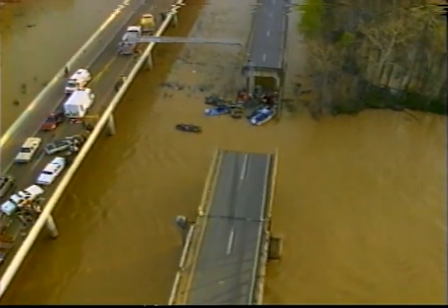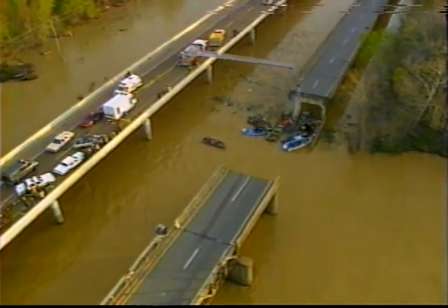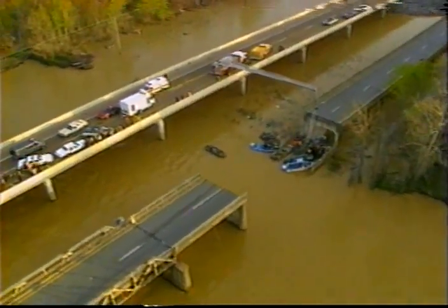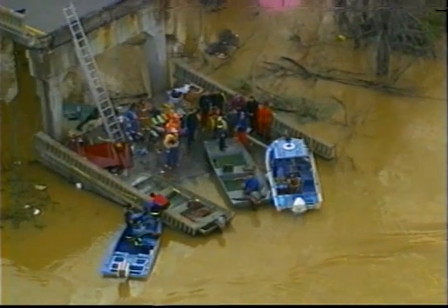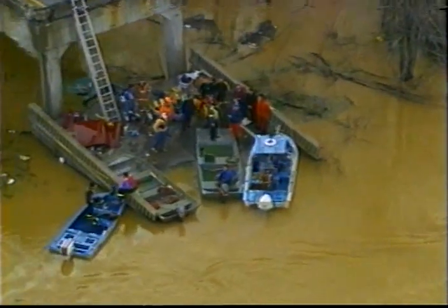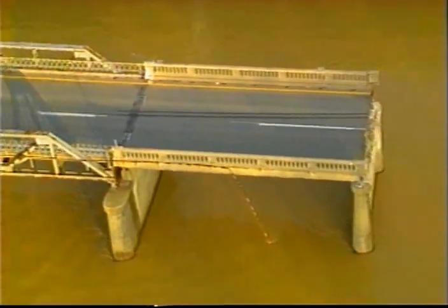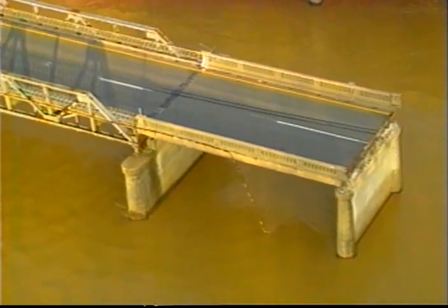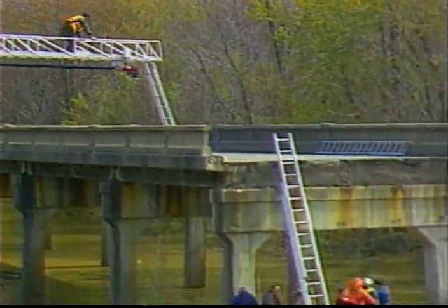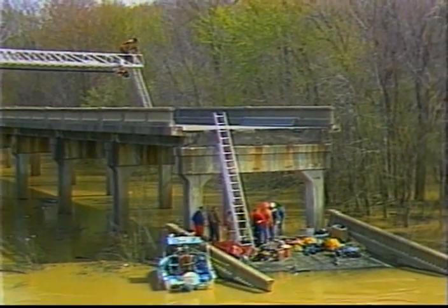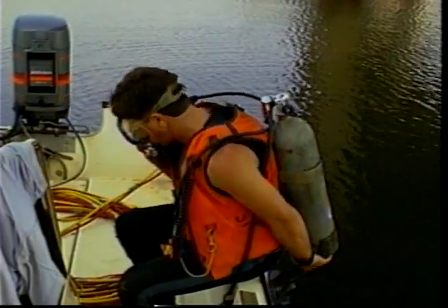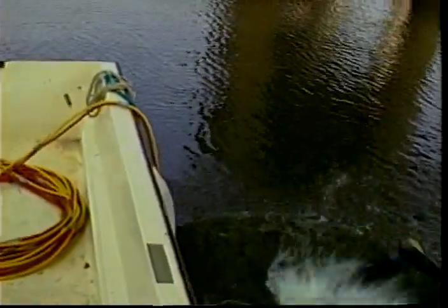Several catastrophic bridge failures due to deterioration of underwater members or foundation scour have resulted in loss of life and focused attention on these problems. As a result, a 1988 revision to the National Bridge Inspection Standards established requirements for the inspection of underwater bridge members. Underwater inspection must now be performed at least every 5 years by a qualified underwater inspector. However, where the water environment is very harmful to structural members, more frequent inspections are recommended.